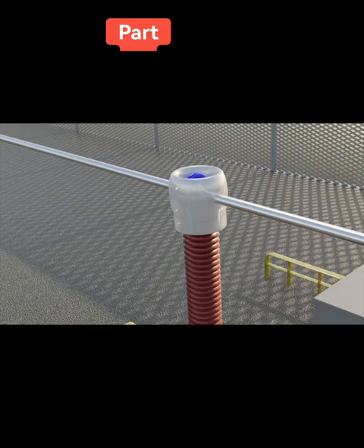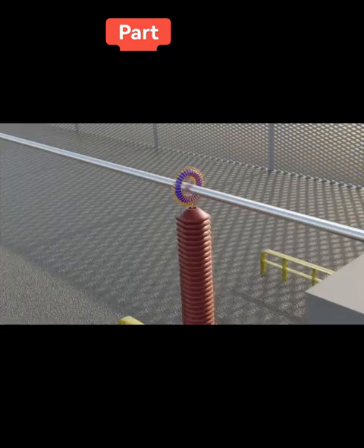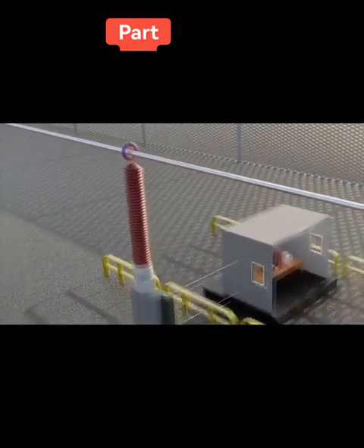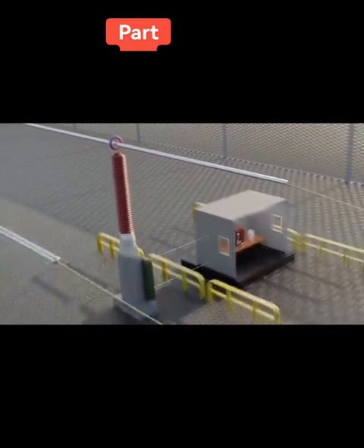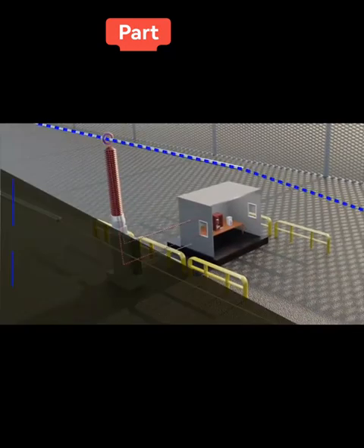In fact, impossible. Now the CT is very much like a standard transformer, where the line is the primary and we can construct a secondary with the number of turns we require to step down the current. Now, we also have the second part, the electromechanical relay.